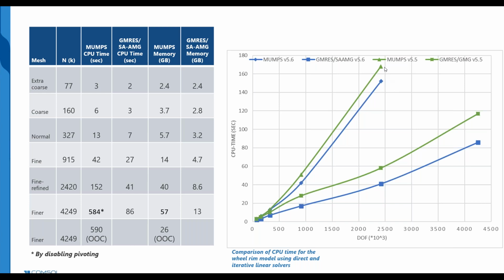You see here that I have both the direct solver behavior on top and the iterative solver behavior to the right, with the more benignly leaning slopes here. So for all problem sizes, the iterative solver is beating the direct solver, both in memory and CPU time.